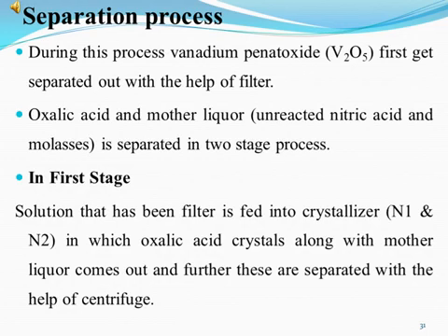At the first stage, the filtered solution is fed into a crystallizer, in which oxalic acid crystals come out along with the mother liquor, and further these are separated with the help of a centrifuge.